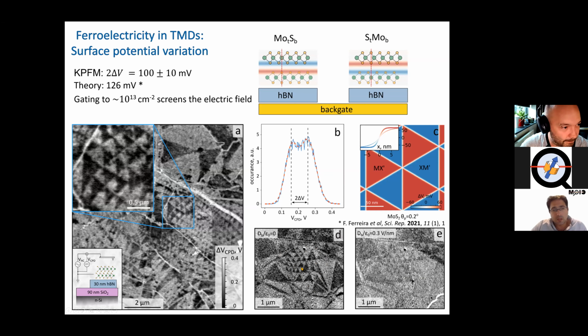I see. Okay. There was also a question, how did you calculate the doping level? Oh, that is from transport measurements, basically, and the thickness of the boron nitride. The boron nitride here is the gate dielectric, so we know the thickness, and we use a flat capacitor model, and we take the conduction band threshold value from the transport measurements that we did. Okay, thank you.